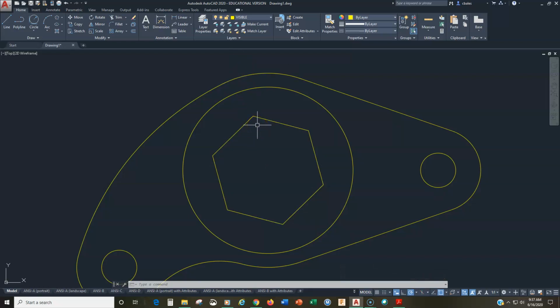Okay. So when you use the rotate command, always start from an angle you know, unless you know just how much you're going to rotate it. And we did not know that because of the orientation that it was in. Always start from an angle that you know, and in this case, the easiest one is the horizontal, which gives us a base point. All right, so that's it.